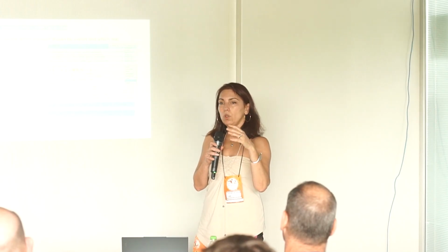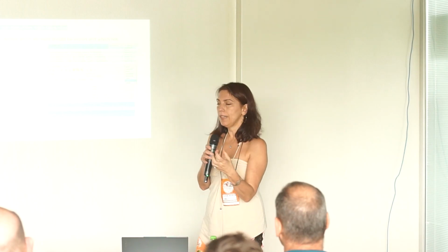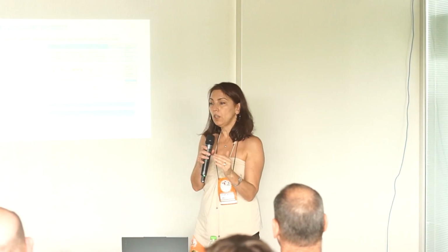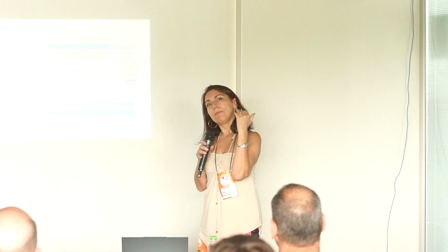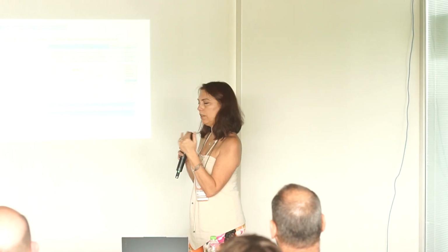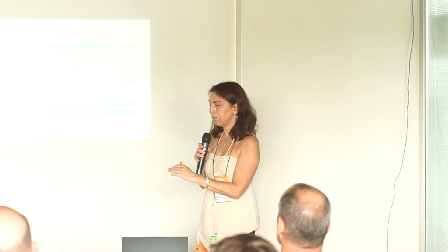Depending on the EPA type that you choose, you then have to inform different parameters, and these attributes that you have to inform are according to the parameters that Epanet or SWMM needs.